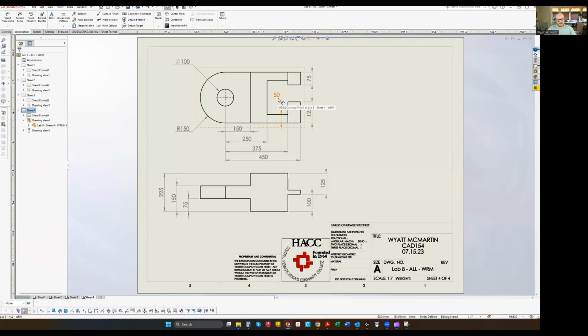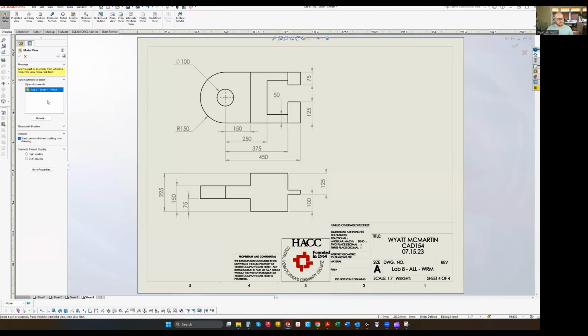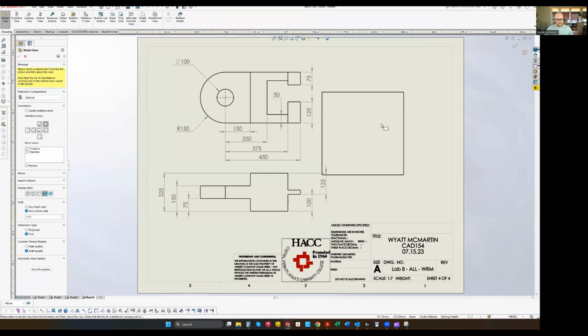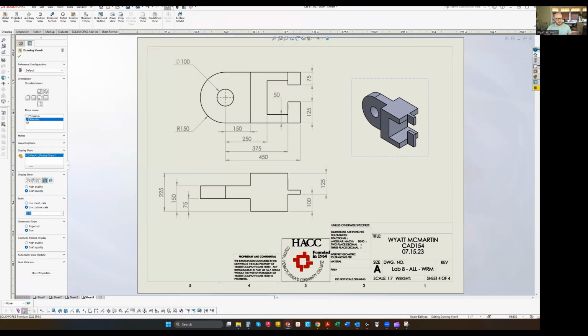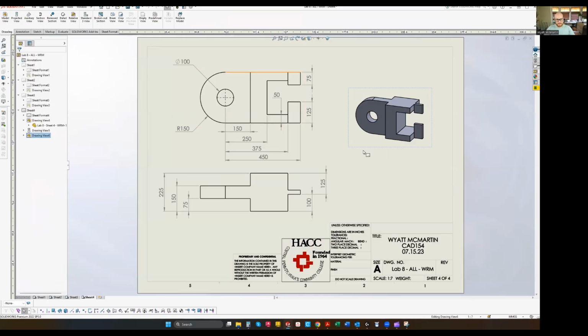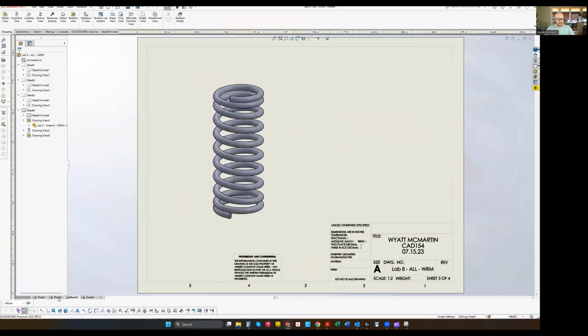And to do that, I just did a little custom text position and made it the horizontal option. And with that, we got one more thing to do. Let's go ahead and add the model and shaded isometric. We're going to grab an ISO, shaded, just like that. If you want to match the drawing exactly, it's more of a dimetric view. And with that, we have all 4 sheets, you can see.